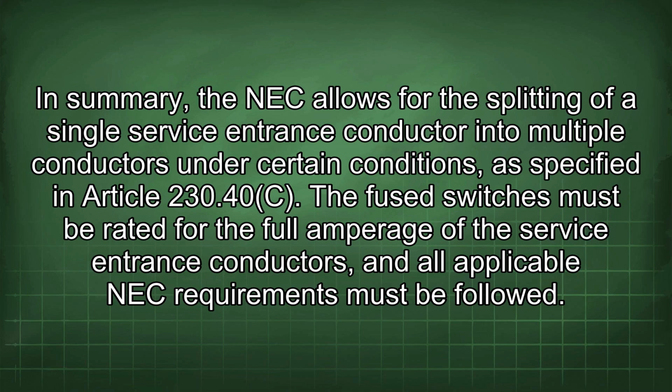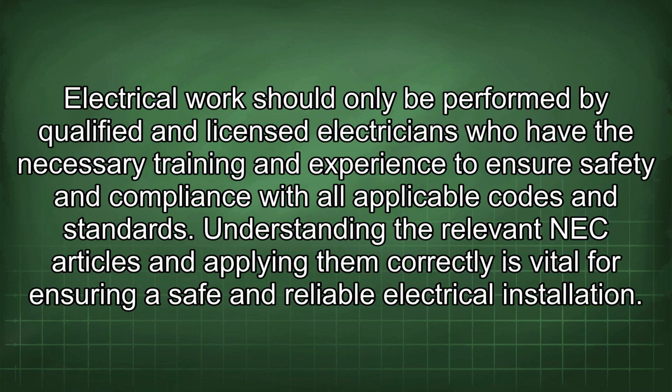as specified in Article 230.40(c). The fuse switches must be rated for the full amperage of the service entrance conductors, and all applicable NEC requirements must be followed. Electrical work should only be performed by qualified and licensed electricians who have the necessary training and experience to ensure safety and compliance with all applicable codes and standards.